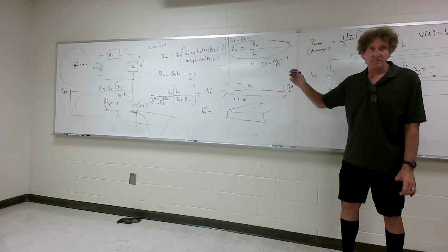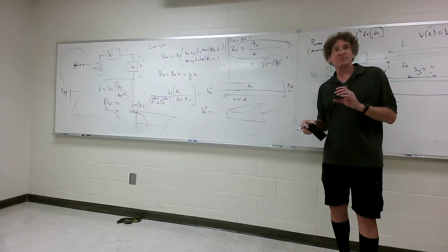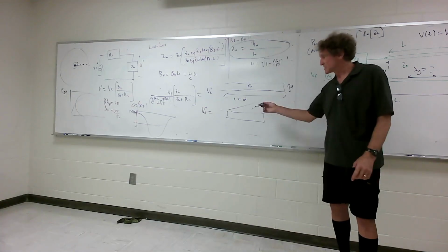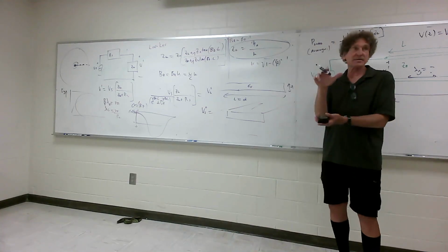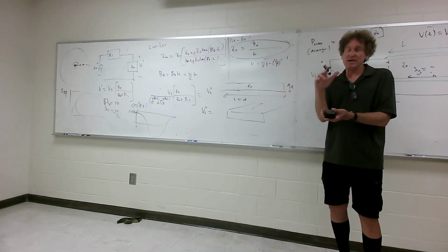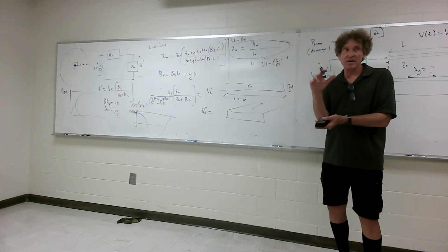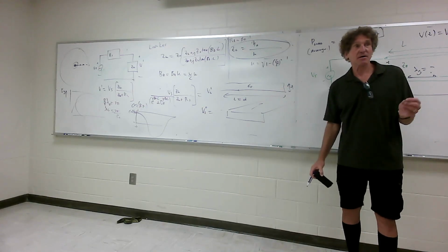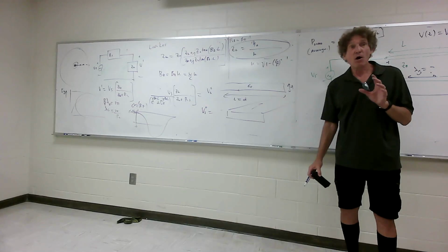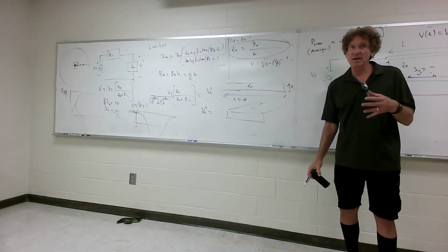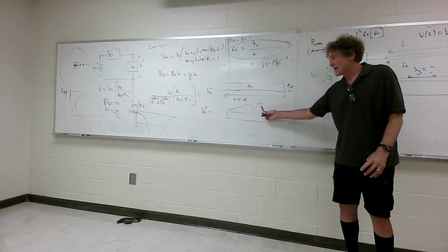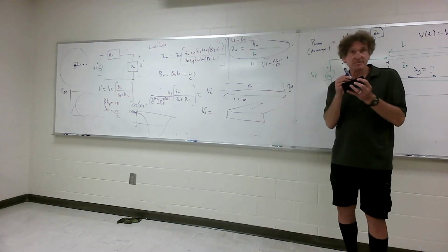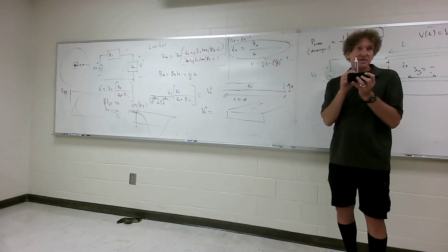And what the guide really does, you might say, is act as sort of like capillary action, or like a surface tension, that it holds the wave inside the guide. That's sort of the way we can show this with the equations that we solve. And the wave just bounces down the guide. But the weird thing is that a slab waveguide has no lower cutoff for the 1-0 mode. Even when you're getting very low frequencies, that guide will tend to hold the wave and it will just propagate more or less centered on the slab.